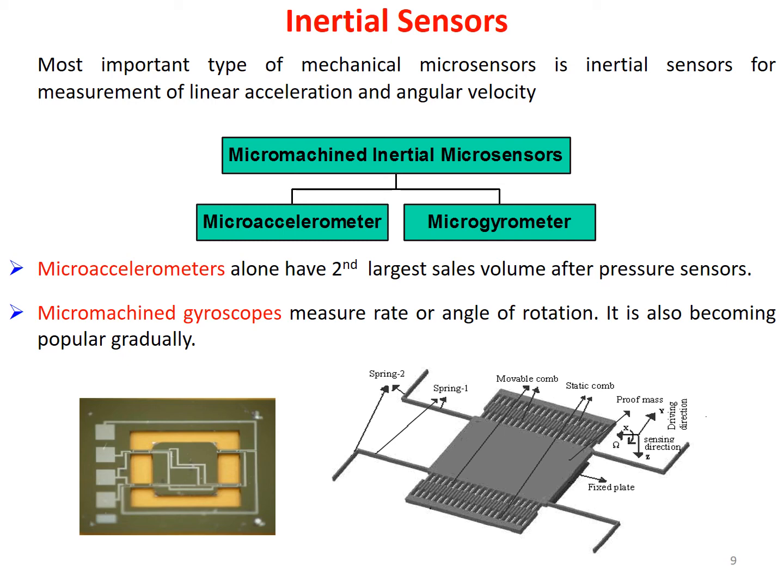So that thing we have to test. That means for the accelerometer we have to ensure the input-output characteristics. So what is the input? In case of accelerometer the input is the acceleration and the output will typically be the voltage, right? The actual output may be displacement, but we have to convert it into voltage, right? So that is the thing. And here just for representation purposes we have shown these two diagrams. Okay, is it okay about the introduction of the inertial sensors?